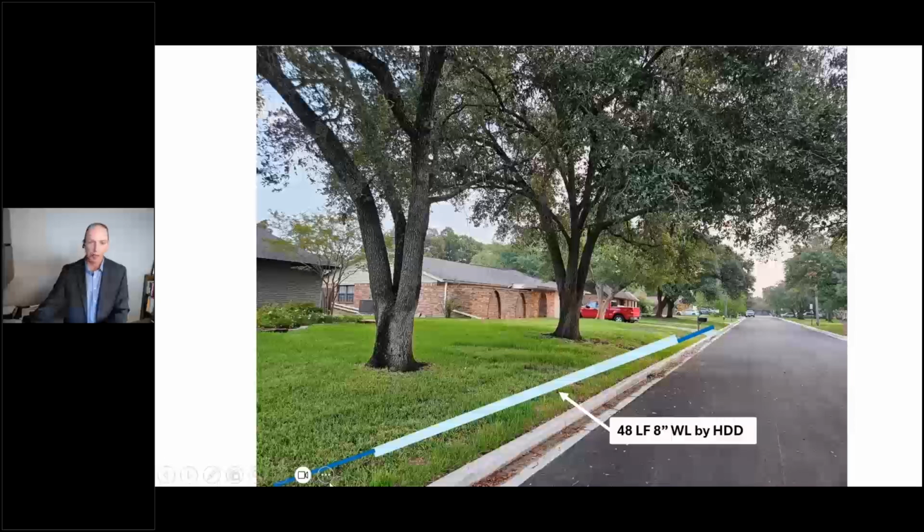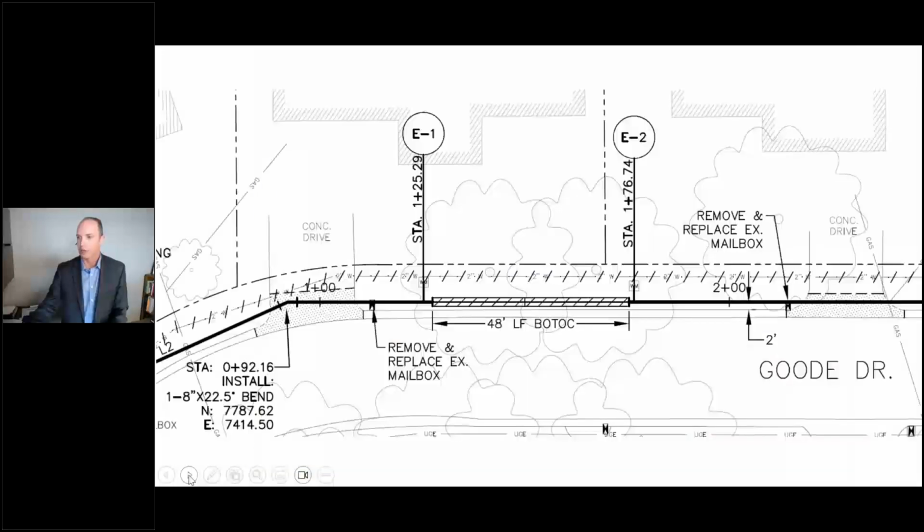I think this particular existing water line was only a 2-inch water line. Where we had 6-inch water lines in the neighborhood, we were utilizing pipe bursting as much as possible, but you really can't pipe burst a 2-inch up to an 8-inch. So where we needed to replace it with new, larger water mains, we were utilizing open cut and directional drilling. Again, this is the typical example of areas where we would use directional drilling on this project. This is the plan view of that same area.